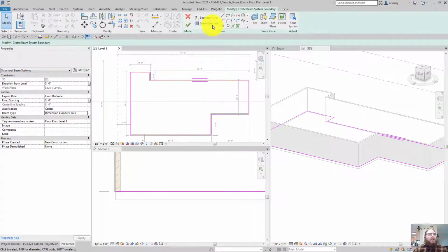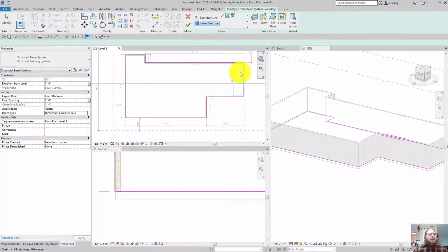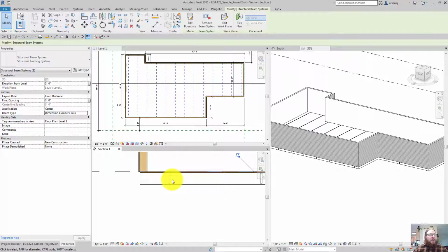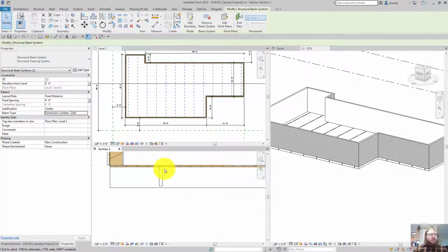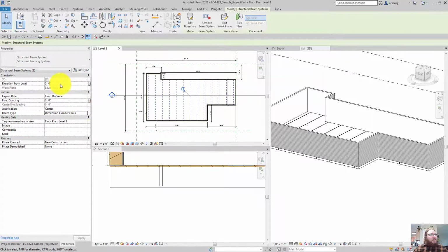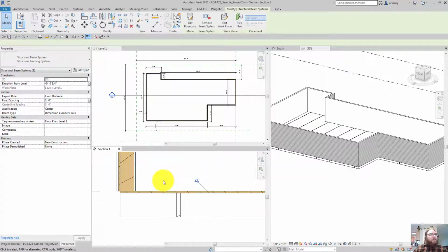And so let's set the beam direction. As you can see, we'd have the joist running in this direction, which would not be practical. So we'll set the joist direction this way. Once we hit OK, it's actually going to populate all of our beam joists, or all of our floor joists. And as you can see, it's actually in the plywood layer. But right now we have this whole beam system selected. We can hit negative 0.75 inches, and it will move all of our beams down into the correct location.